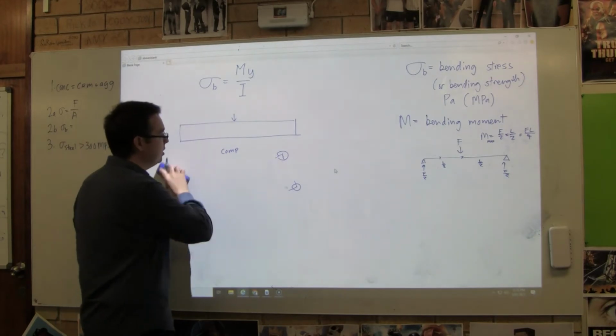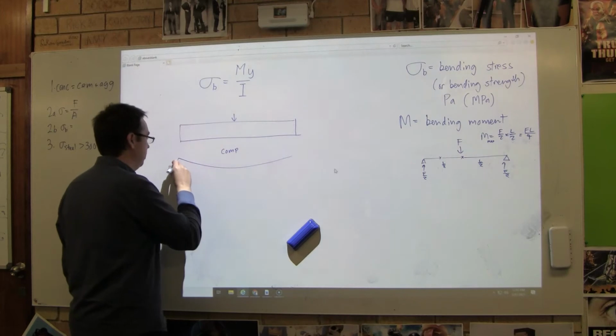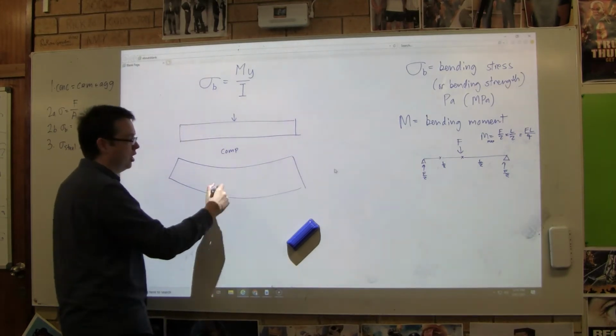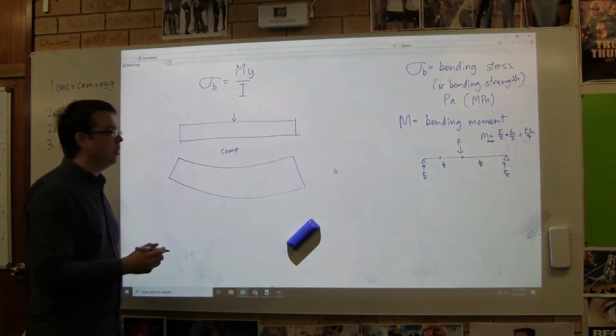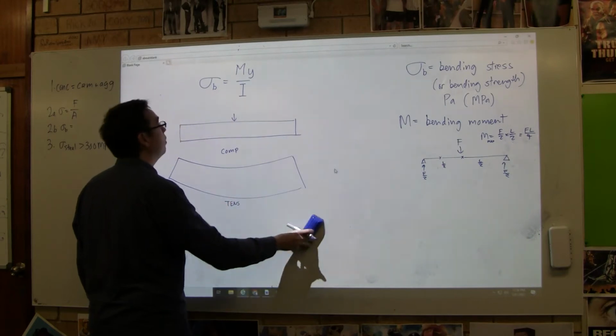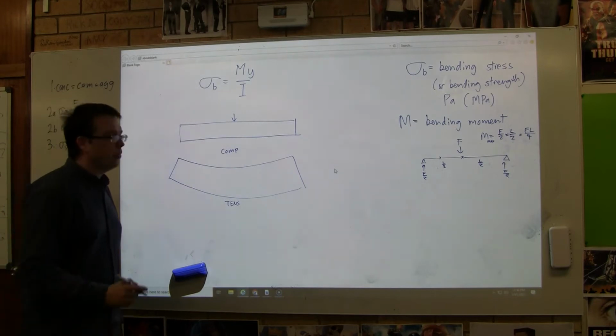And if you actually take a piece of timber and bend it enough, you'll start to see it split apart, where it will crunch at the top and stretch and get cracks on the bottom. Concrete usually fails on the bottom, right? That's how we design it. We under-reinforce it on the tension side. Okay, now here's the thing.